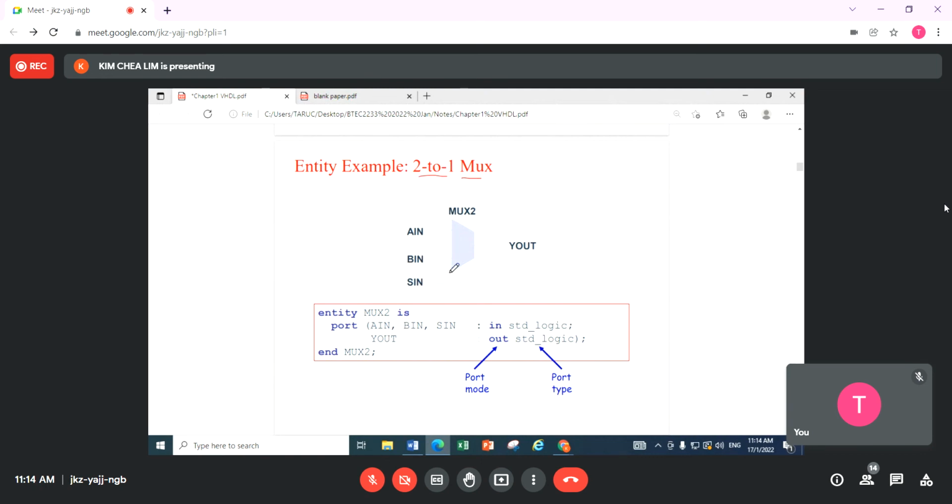So in my multiplexer here, of course, I must give it a name. In this case, we call it Mux2. Some of the students will ask me, why don't you call it 2Mux? Why call it Mux2? Why never say multiplexer output 2 Mux 1? The answer is, do we need to tell the output? All multiplexers got 1 output only. So no need to tell.